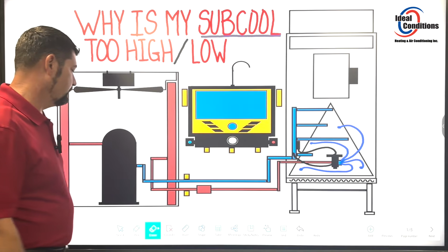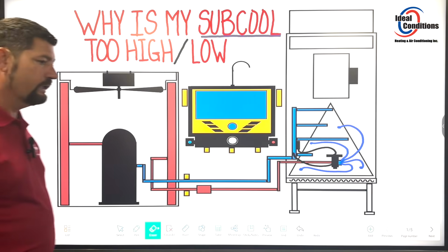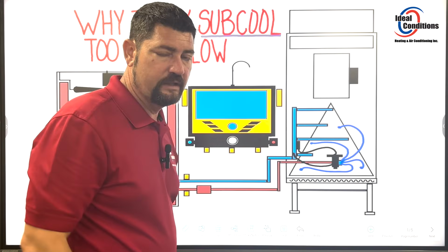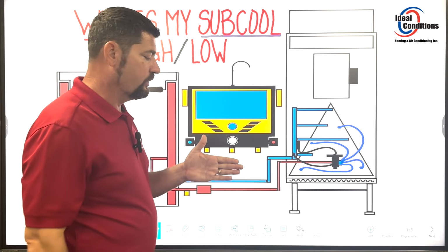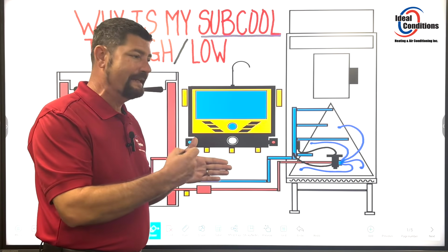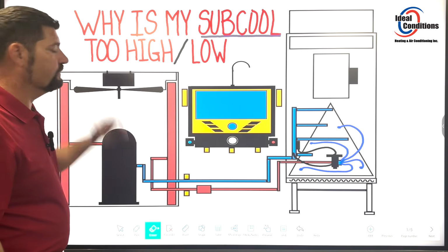And there's a wide selection to pick from that can make that happen still. All right? And so, if I left dirt all over this coil, there's no filter I can change. If I left dirt all over that condenser coil and I never hosed it off, I can't sit there and go, "Well, I can see through it." Well, okay, I'm glad you can see through the fins. That doesn't mean that the plate on that fin is not corroded and unable to transfer the heat and reject the heat off the tubing and into the airstream.